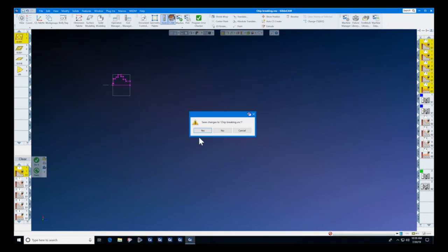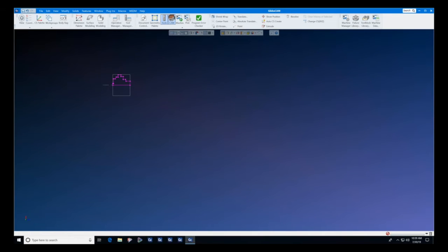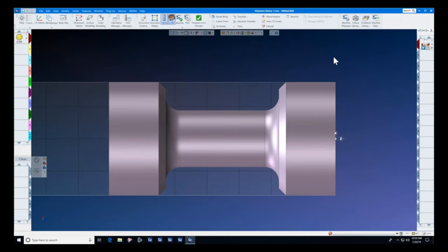Let's look at volume turn while we're here and talking about improving our turning. We all know what volume mill did for our milling. Volume mill allowed us, when we're milling with end mills in confined spaces, to increase our production by a factor of 2, and to increase our tool life by a minimum factor of 4. And many times we can go to tool life greater than 7 to 10 times. Well, now we have volume turn.